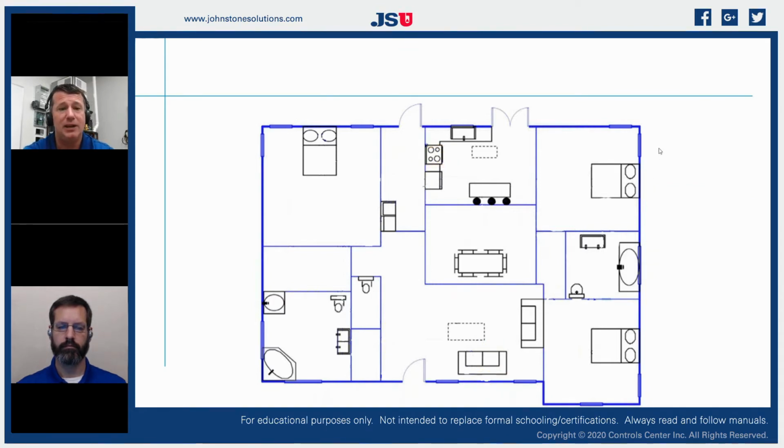I was reading an article this week about how a 1,500 square foot residential structure has changed in the last 50 years. Fifty years ago, if you had a 1,500 square foot home, you looked at it as CFM per square foot, so I needed about 1,500 CFM. That could very realistically end up with a 100,000 BTU furnace and a 3 to 4 ton air conditioner. Today, you can create the exact same 1,500 square foot home that can run on 5,000 BTUs, if the proper materials are used for it.